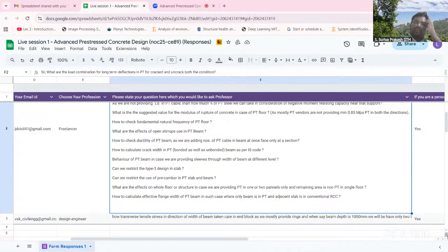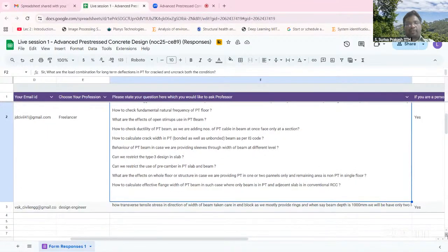In the flexure chapter, we talked about the moment curvature analysis, right? In moment curvature analysis, at ultimate you can find out the curvature of the section. From the curvature at ultimate and the yielding curvature, we can measure something called curvature ductility, right?